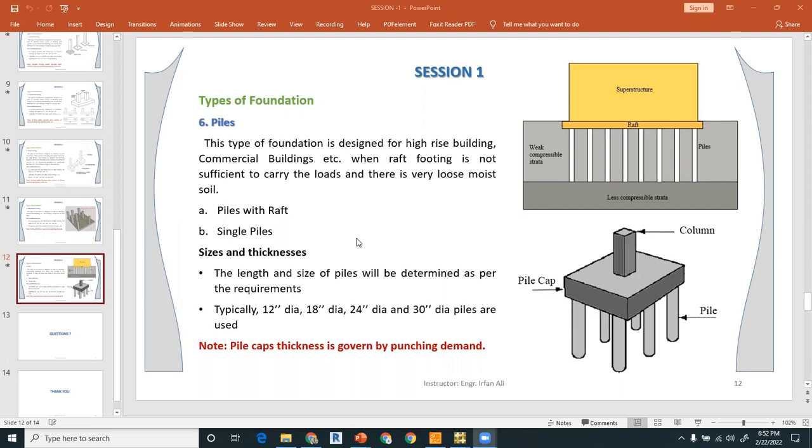If you only want to transfer the load from the superstructure to the walls, and then from the walls to the footing, then you do not have to design the walls. You are talking about the design, right? Design is something else for the brick masonry. So you model the walls in ETABS and select the brick masonry material, so it becomes a brick masonry wall. Then you apply the loads on the superstructure, and those loads transfer to the walls, and then the wall transfers them to the footing, and then you design those footings as a wall footing.